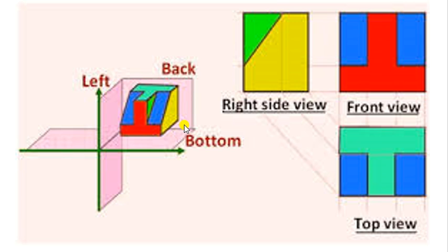If we are watching an object from the right side, then we will get its projection on the left side, that is the vertical frame on the left side of the object. Here you can see the very first left side view in this projection drawn in the left top corner.